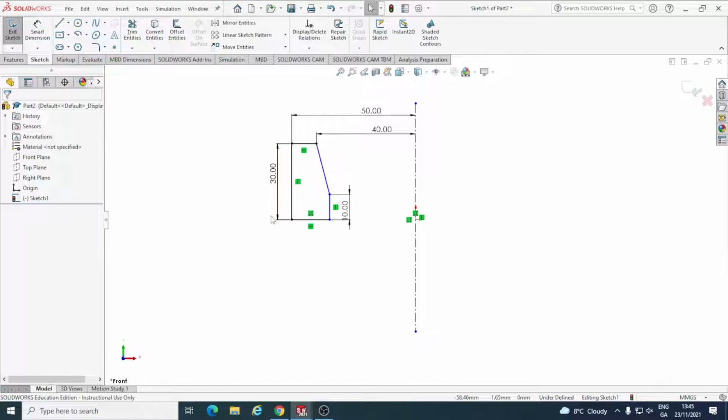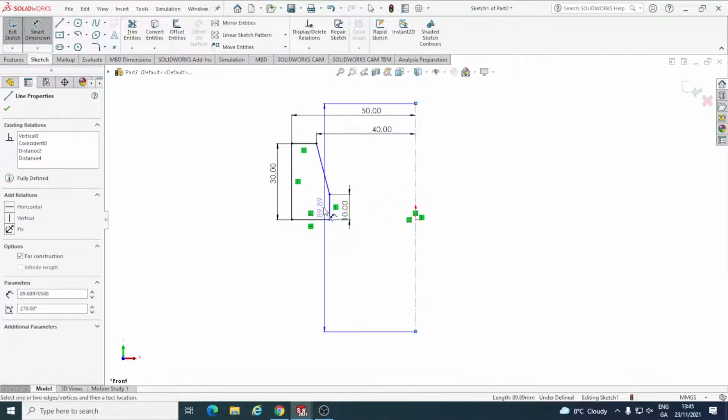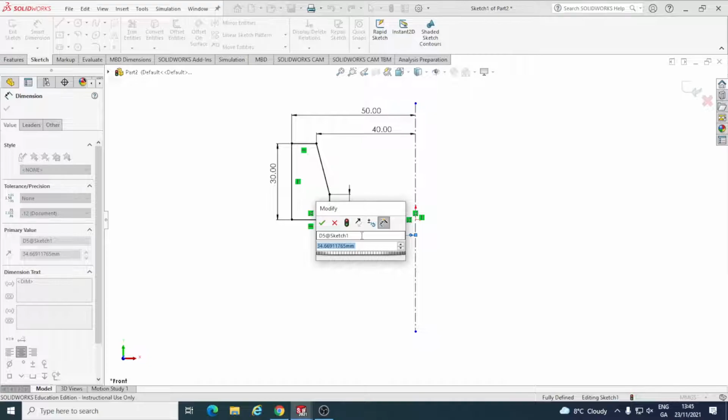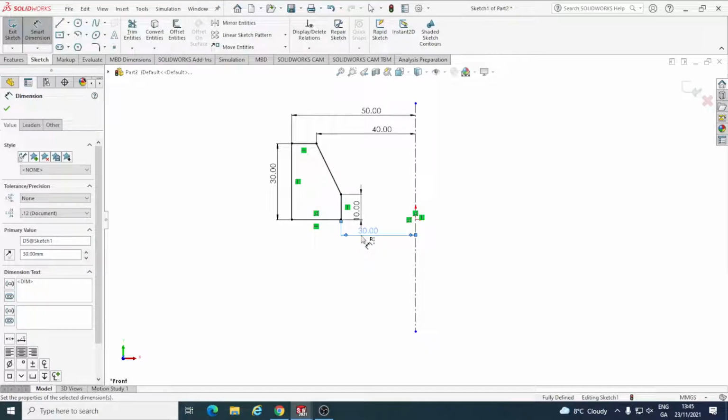Okay. Now the last thing I have to do is put another Smart Dimension over here, from the center line over to this point here, and that is going to be 60 diameter, which is 30 radius. That now is my ring. So if you can imagine part 5, we're just looking at the bottom left hand corner of 5, and you can see that that's the profile.